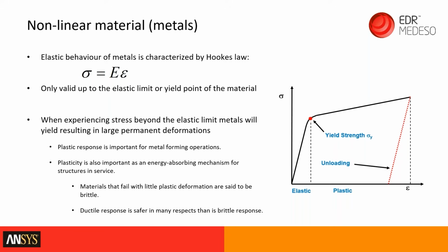Approximately 90% of customers, I don't know the exact percentage, are working within the linear range of materials. So if you imagine working with steel, for instance, or other engineering materials, they have this elastic range. Below the yield point, the material behaves in almost an elastic manner. This is due to the ionic bonding being stretched between the different molecules in the metal, and then as you release them, they just go back, and they obey Hooke's law.